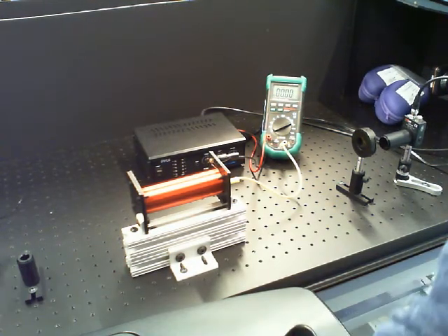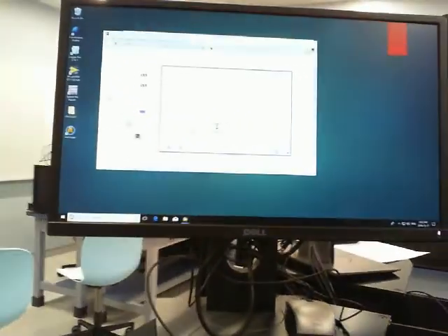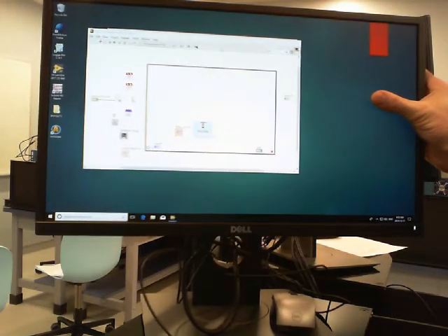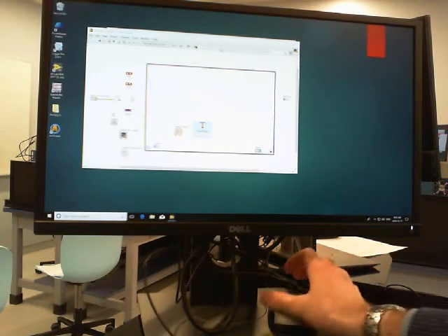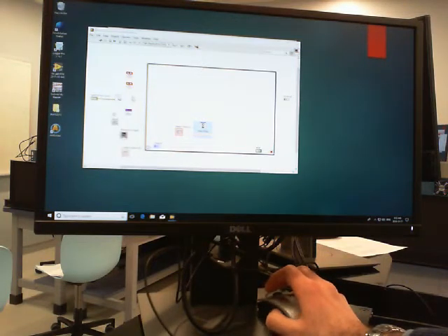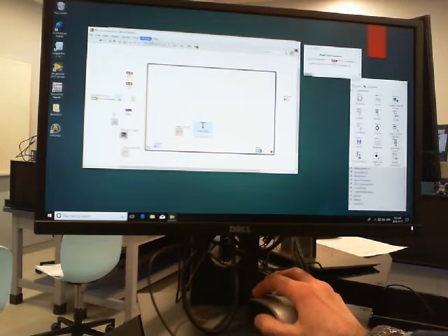And so you'll be using LabVIEW to create a software lock-in amplifier. So you'll be given some starting point for your program, probably something like this. And I'm not sure how much you'll be able to see on this video, but this is the LabVIEW interface, which you've used in the past. This big block here is a while loop, and any parts of the code which are put inside this while loop will just run over and over and over again. So it'll just cycle through whatever code is in here. It'll execute all the commands and then go back and re-execute all the commands and keep looping through until you press the stop button, which is on the front panel.